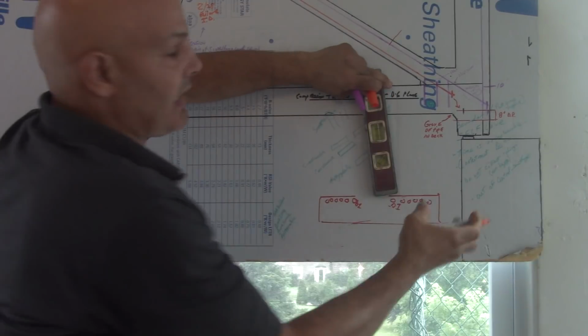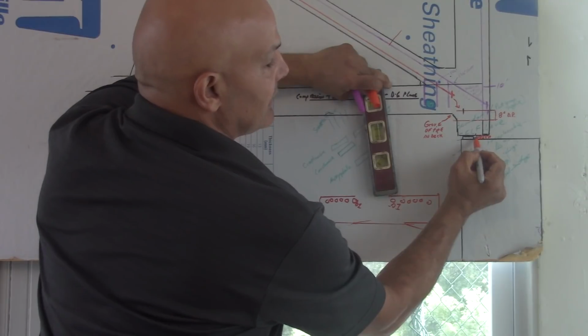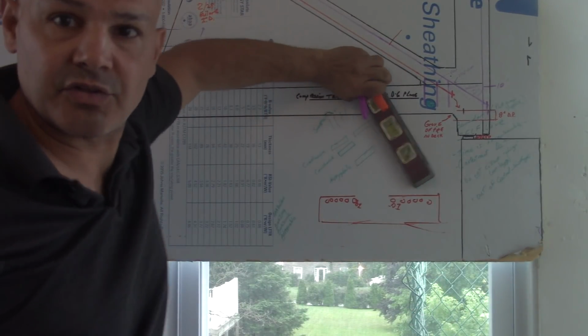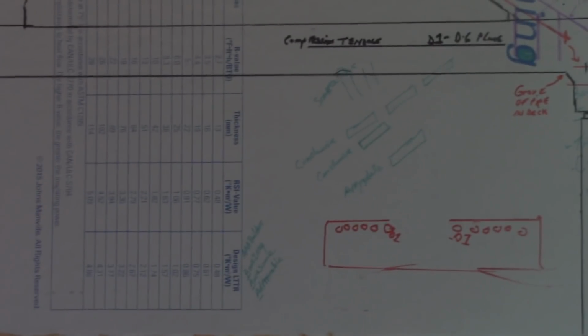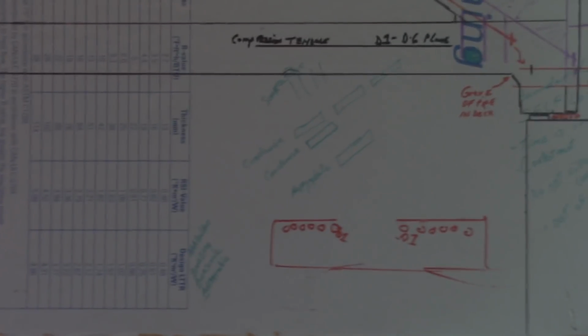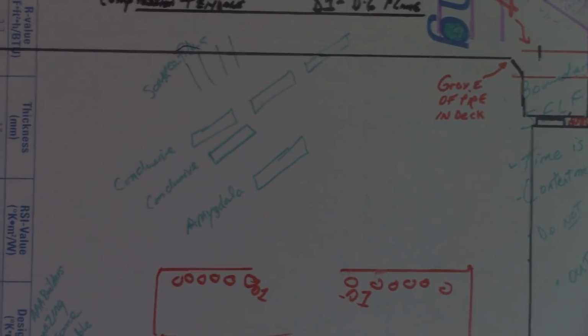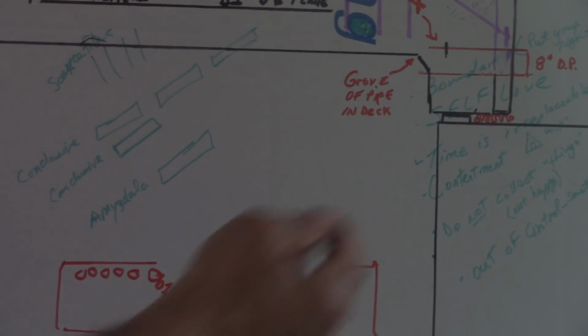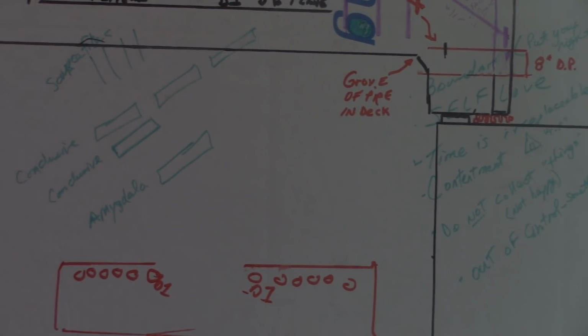This is the issue about grout. So this is a shim, guys. This will be grouting, if you will. Let me do that for you. Grouting would have stopped that. Let me get you zoomed in a little bit. Well, I think that's plenty. Maybe not. So grouting would have stopped that from falling down. Let me zoom in a bit. So grouting would have stopped this from falling down. We see that in the OSHA video images where this is 4 inches on one side, 4.5, almost 5, and over here it's 3.